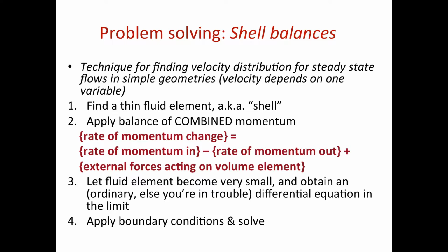However, in many cases, when you have the most general equation, it can be quite burdensome, and you don't get to visualize and analyze the problem properly. So shell balances give you a little more hands-on understanding of the physical problem. That's one reason to use shell balances. The second is that as you're putting the shell balance together, I call it an onion, you're working layer by layer on your problem, and it's often easier to solve the PDE that way. Whereas when I have this humongous nonlinear PDE that I'm trying to solve and I throw in all of the possible partial derivatives, it's going to be hard to solve unless I have a numerical simulator on hand.